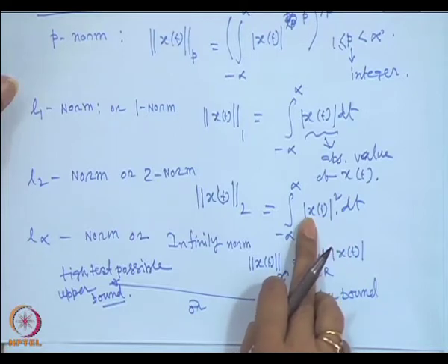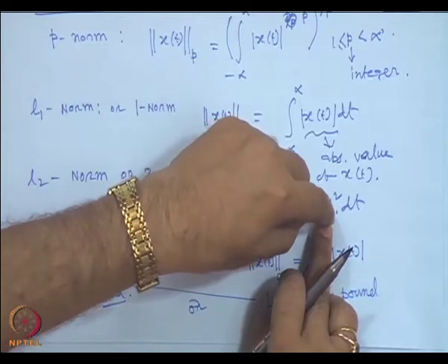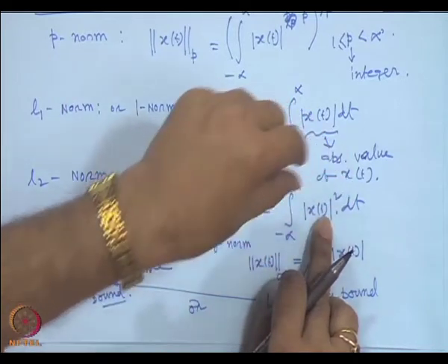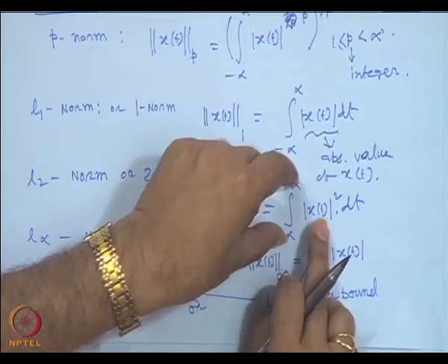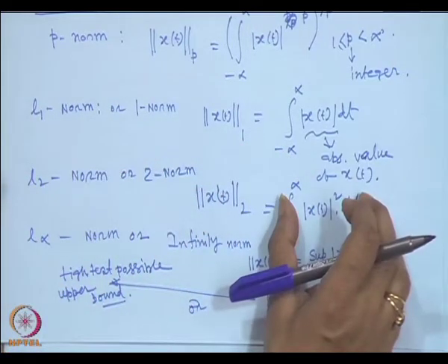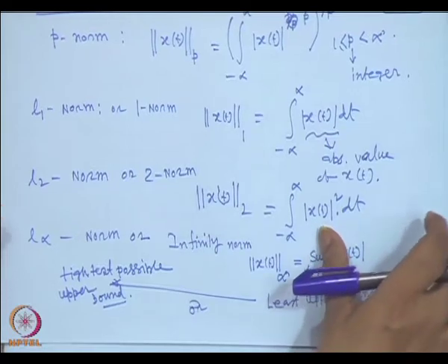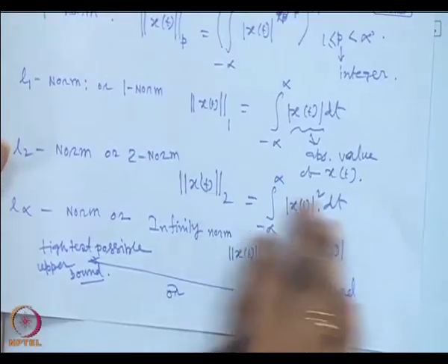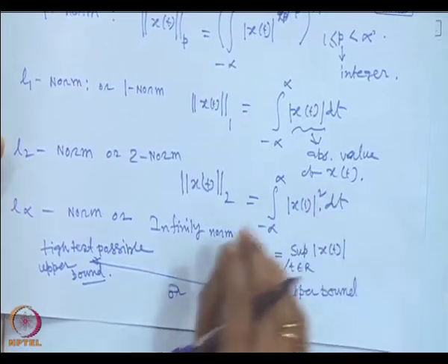That means x square, the signal squared, multiplied by a resistance R equal to 1, so it is a power, and I am integrating over that interval from minus infinity to plus infinity. So, this is the energy content in the signal. We use the power content expression when that x of t signal does not tend to 0 as t tends to infinity; then you will use the expression for the power signal concept.